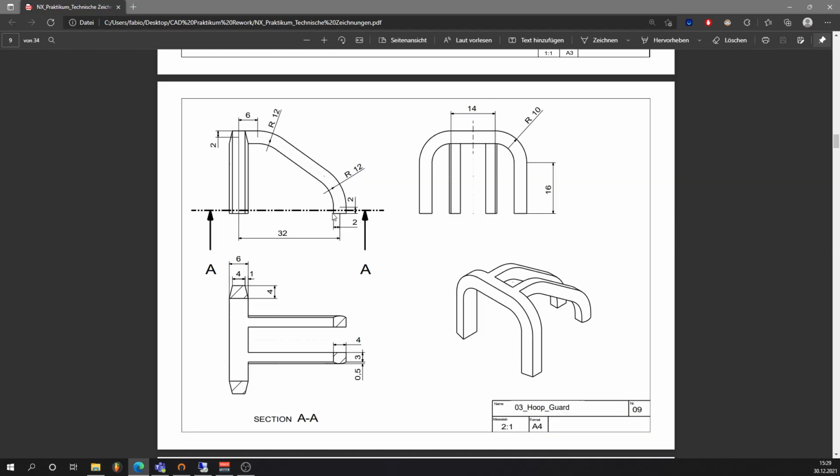Seeing this line right here screams for the sweep along guide function, or the swap function, which are 2 new functions that we're going to learn today, and that will help you model a little complexer things than just by using extrude and revolve. Still, extrude and revolve will be the more important ones for the exam, but you definitely also need to know this one, and it's no big deal anyway, so I'd say we just jump right into it and you will see how to do it.